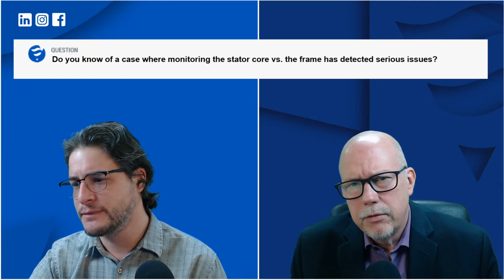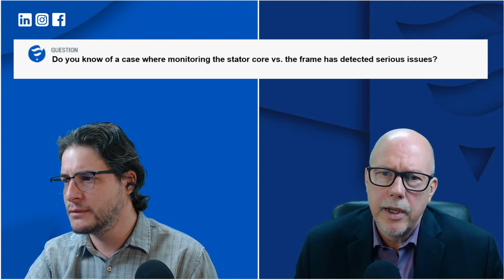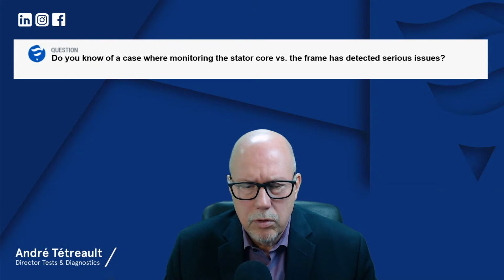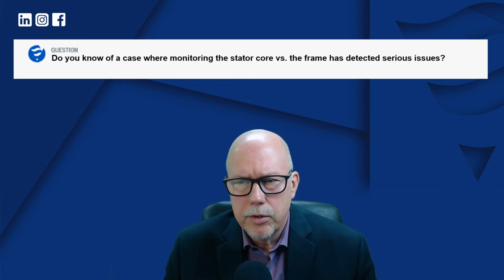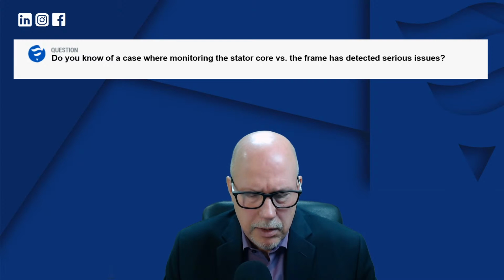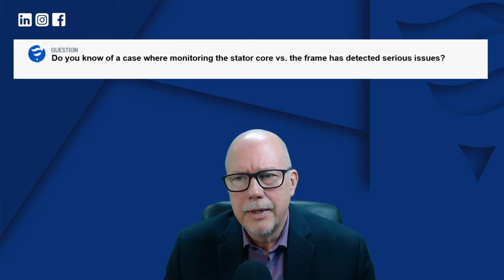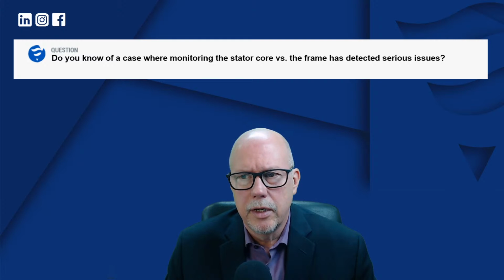Yes, we've had a few cases that we're handling right now. There's a large coal power plant that we monitor. They had issues for some time, and they replaced the stator recently. So we're trying to see if the new stator has the same issue. It doesn't seem to have, but the older one did have an issue where the core seemed to be loose from the frame, and they had arcing issues.